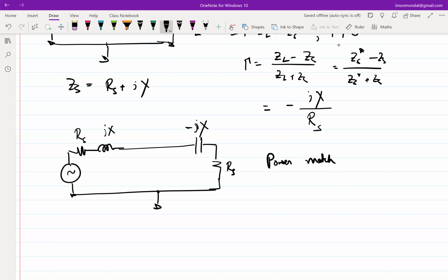That's the consequence of it, right? But fortunately, in most real systems, it's not the case, because the antenna can in general be modeled as mostly a real impedance. There will be some remnant of imaginary part, but that's okay. So this is a power match, but not a reflection match.